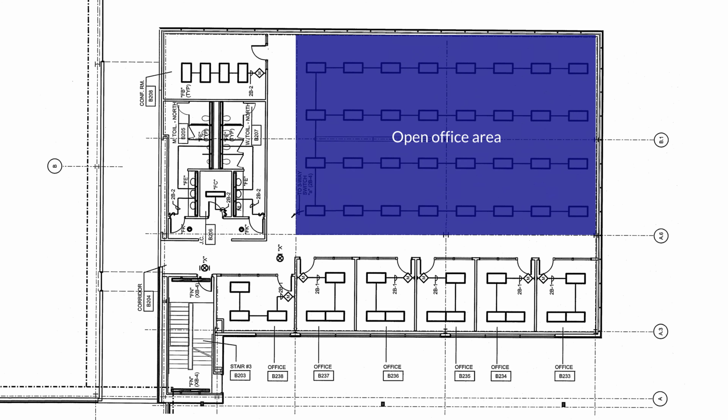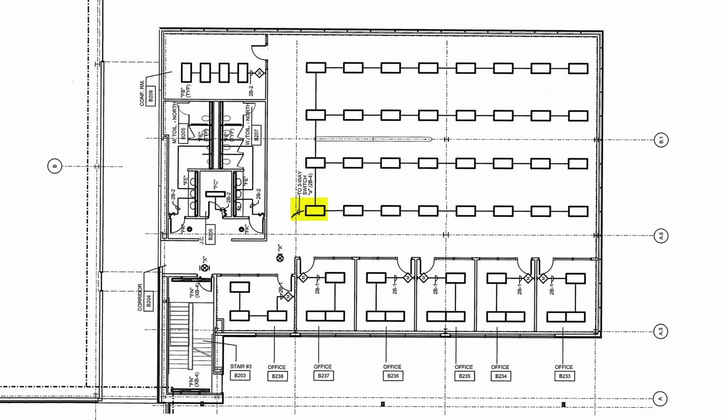The original circuit directed power to every fixture in the open office space, with power entering the circuit near the lower left fixture. This circuit will need to be altered to enable 4 distinct zones for each of the advanced load controllers being installed in this space. To create these zones, the circuit will need to be broken into these locations and re-established as shown here.